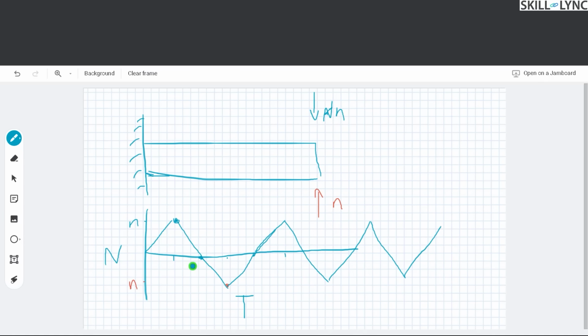So here you can see that at this specific time instant, n value of load is acting in the downwards direction. So we have a positive n value. And according to the graph, after a fixed interval of time, the direction in which n is acting will be reversed, but the magnitude will remain the same. But that is not the case with variable amplitude fatigue tests. With time, the direction and also the value of the acting load will keep on changing.